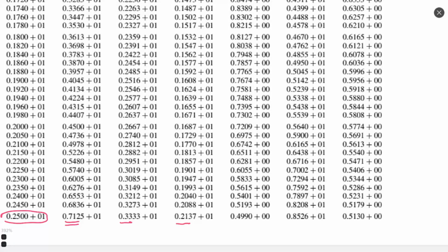Temperature has the smallest ratio, but it does not mean that the temperature rise is small, because, for example, we use pressure in bar. We had, for example, 1 bar before, and after we have 7.1. But temperature we use in Kelvin, right? So if we had 300 Kelvin before the shock wave, after the shock wave we have more than 600 Kelvin. So it's a lot.